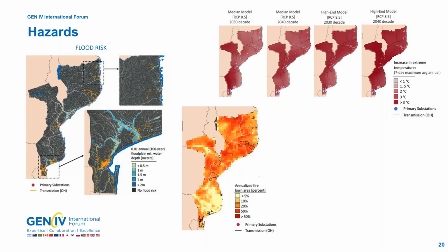And so this isn't representative of the entire country of Madagascar being on fire, but it does represent that there's a high degree of fire risk across all of Madagascar. There's a lot of grassland in Madagascar, and so you get a lot of spot fires that occur in particular regions, and this does indicate that you have to be careful about engineering things to be resistant to wildfire. In countries like Madagascar, and this is true even in the United States, usually what that means is that you have to do a lot of vegetation management around certain kinds of infrastructure like transmission lines. If you don't have any vegetation right up against your transmission infrastructure, it usually does a good job of being able to withstand wildfires that move through a particular region.